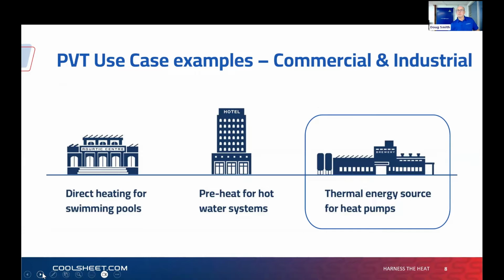Yeah, so there are three primary uses of PVT, certainly at a commercial industrial level. Residential, we can have a separate conversation about that. But direct heating for a swimming pool needs a lower temperature output. It's being used quite a lot around the world, in key pockets around the world, as part of the hot water solution in hotels and resorts. And we're talking to you today about what we think is really going to be quite a driver around the world for PVT, and that's absorbing that waste heat and using it as a thermal energy source to improve the efficiency and the COP of heat pumps.